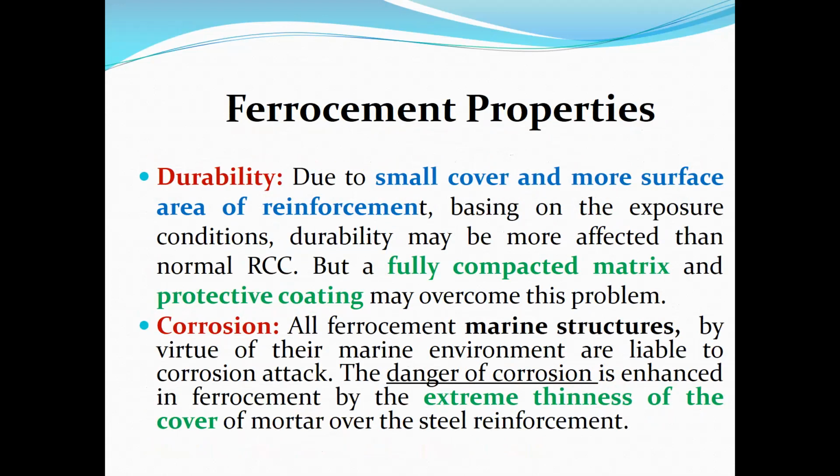But if the matrix is fully compacted and you use protective coating, the problem of durability may be overcome. Corrosion is a major problem for ferrocement, especially in marine structures, because chlorides or sulfates from the environment enter and accelerate the corrosion rate. Since there is hardly any mortar cover, and the amount of steel is very high, corrosion is a problem for ferrocement structures.